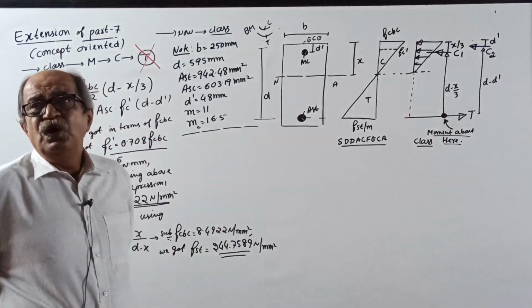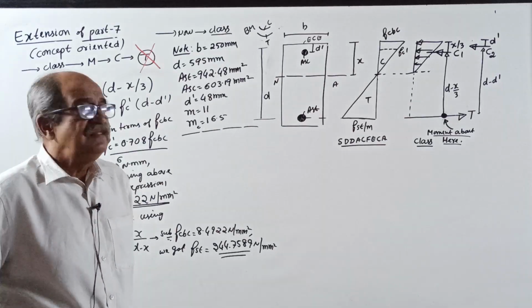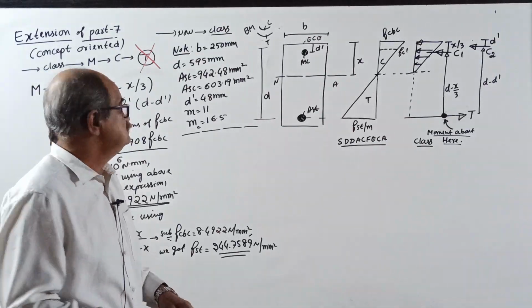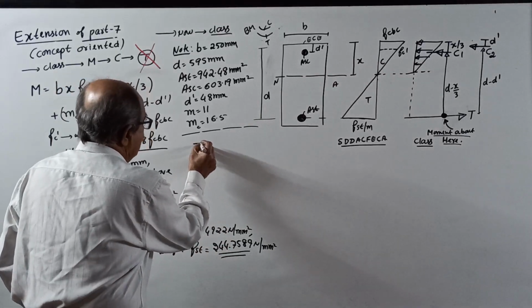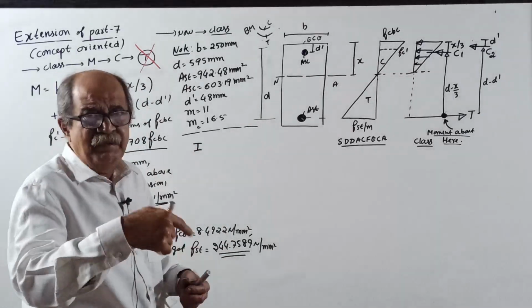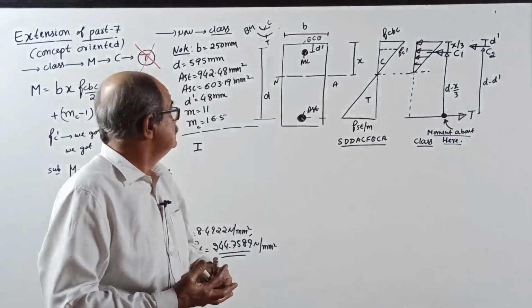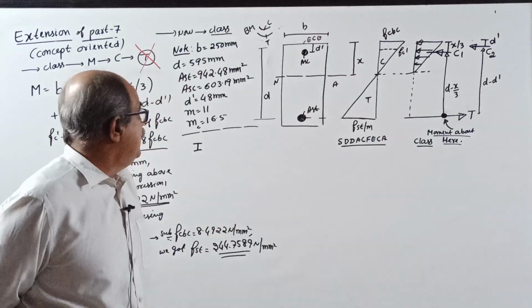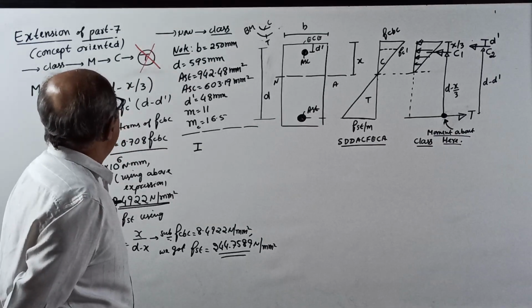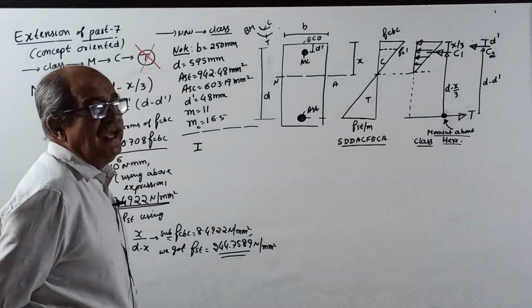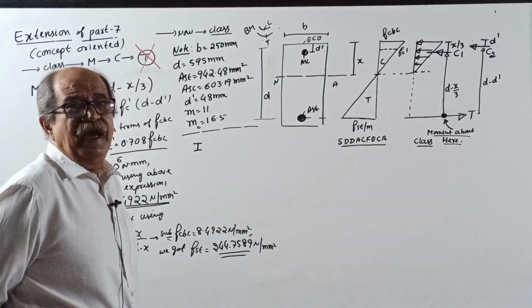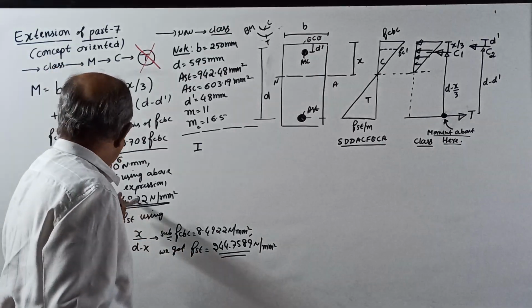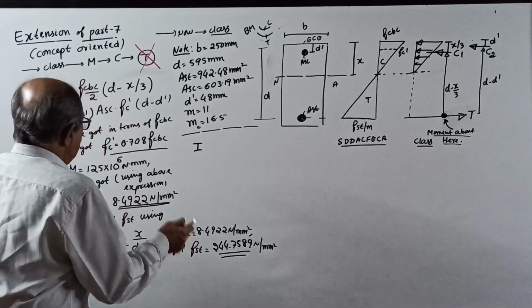Last class, we solved a question. That was doubly reinforced section, stress calculation. Roman 1. Roman 2 is meant for MR coming up in further classes. Question was, a rectangular section of an RC beam, 250 mm wide and 650 mm deep, is subjected to a sagging BM of 125 kilonewton meter. I remember it, 125 sagging BM.